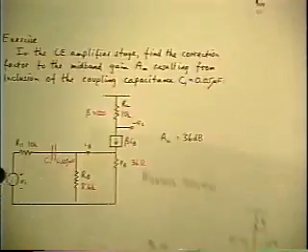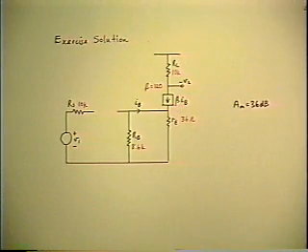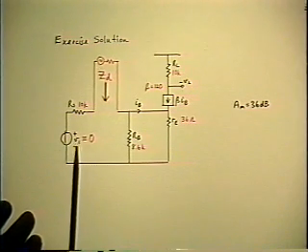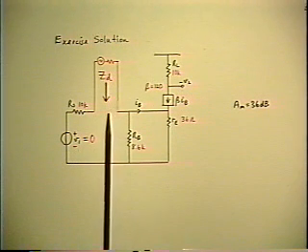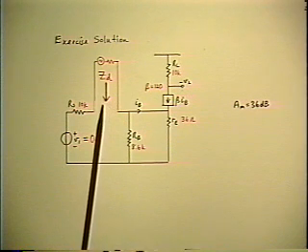So the starting point is you break the branch at the place where you want to add the extra element, and you calculate two driving point impedances. First, the ZD. So you apply a second source and you make the first source 0, and now you calculate the ZD. And this is where you take over. Well, let's follow through the argument.